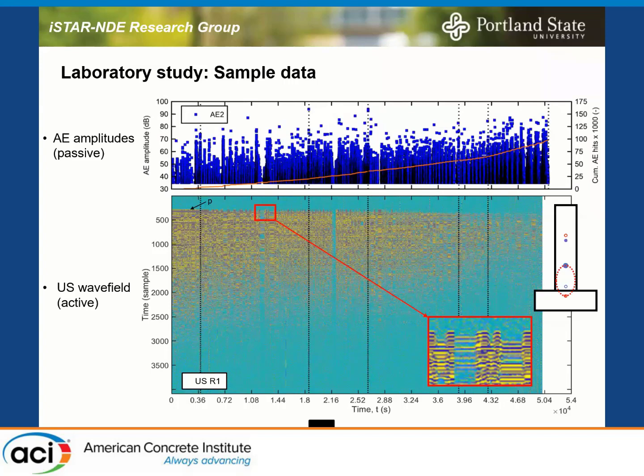The way I showed those ultrasonic regions rather than just a line, is because what we have seen is with coda waves, when you look later in the signal portion, you can really capture stuff that's in a region, not just in the direct path. When you do UPV, ultrasonic pulse velocity, you assume a fairly straight path, and then you don't see much.